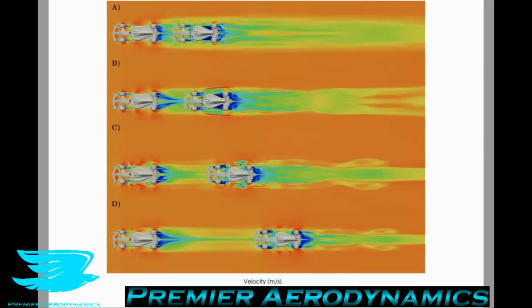as the wake that is generated by the leading car is released far away, disturbing its follower. It is also clear that as the second car gets closer, it inherently enters into a unique wake structure characterized by very low speed flow that ranges from 0 to 10 meters per second. And this is quite alarming considering that the free stream flow is 50 meters per second. So the wake is like not even 20% of the free stream flow.